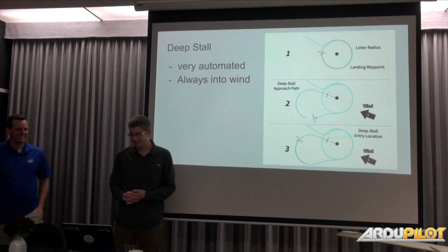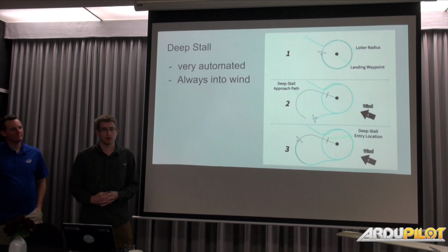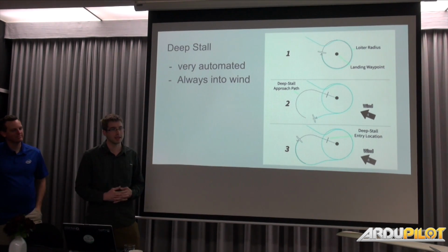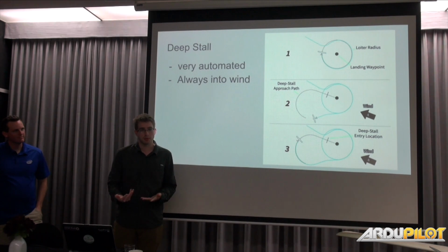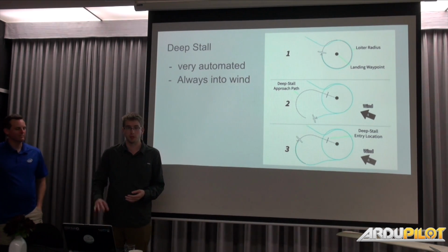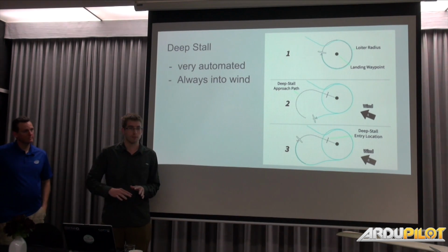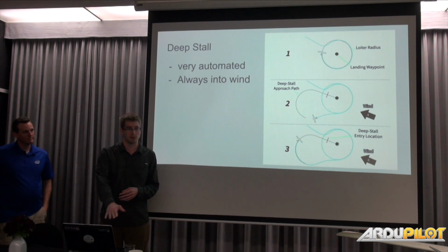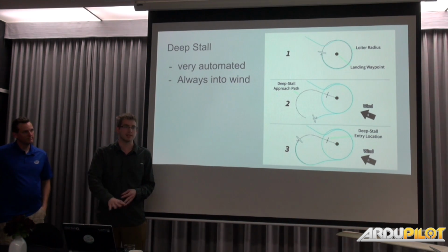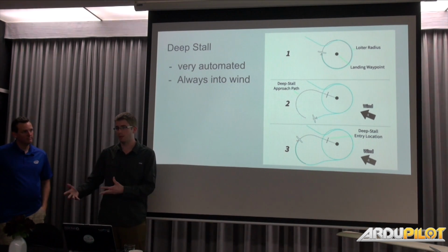Rapid determination. The other thing is that if your aircraft is capable of doing deep stall landing, this has been hooked into from an autopilot side. So this is actually connected to AFS. So you can terminate your aircraft with deep stall at any time. So you can actually use this from GCS to say, terminate my aircraft. This is useful from a safety perspective because this is far lower energy than spinning the aircraft into the ground. It's much easier to say, just enter deep stall, it's a stable regime. We know what our maximum energy is when we hit the ground. We'll try and steer. So this is actually hooked to the AFS library if you want to use it that way.